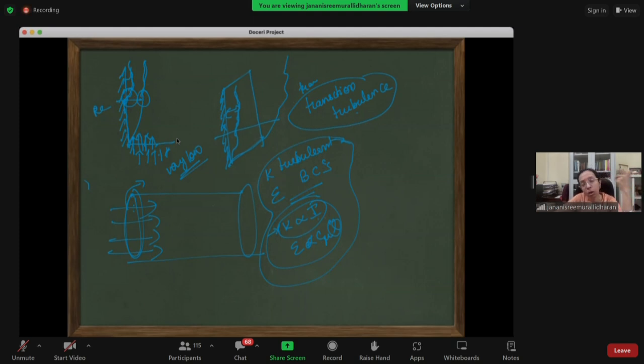The other thing to monitor, if you're looking at a pure CFD question like this, is that I would solve it as turbulence, and I would monitor the K and epsilon values to see if it is also having turbulence. And the critical Rayleigh number, meaning is it purely natural convection? That I will also monitor by looking at the temperature profiles.